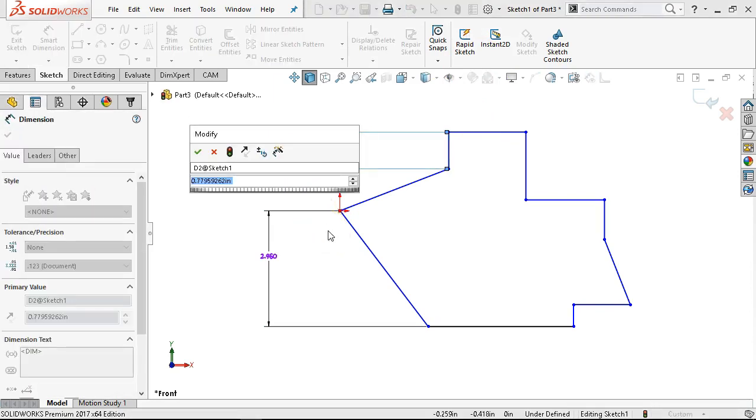We have a decision to make. Is the stack up of our tolerance consistent with the rest of our parts? All right, 4.6 is not really a number, and since it's coming to a point, it kind of depends on what kind of angle it's generating. But 3.8, I recognize 0.38 as 0.375. If I have enough 0.38s, 5, 10, I'm going to gain 50 thousandths over 10 segments of that 5,000 shift, putting them in 0.38 rather than 0.375. So if your stack up of tolerances is critical, in this case I'm thinking it's not, but this is where I put that